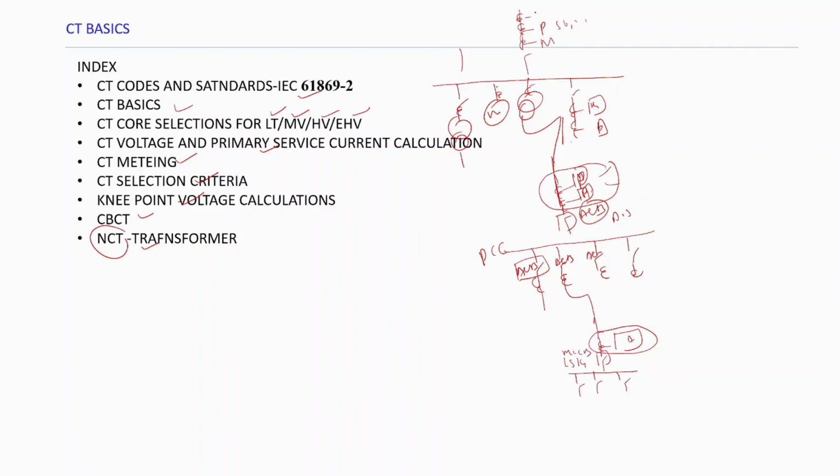Here I am using it for the cable differential protection. Here also I am using the 3 core CT sometimes. What is that other CT? That CT will basically be used for bus bar differential. So as we go from LV MCC to PCC, then to medium voltage switchgear, my protection requirement goes on increasing. For 11 kV or 33 kV, bus bar differential will also be used. That is called a special core CT.